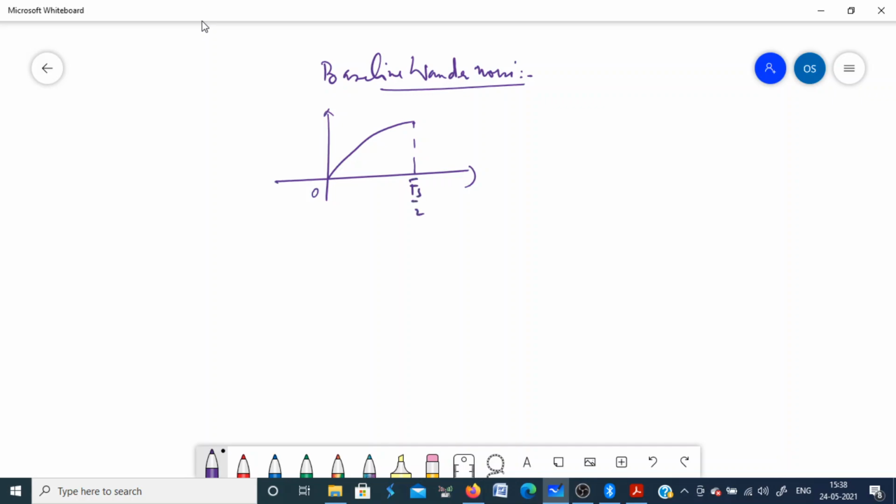Okay, then we modified it somehow. We got another response like this. So at a frequency of fs by 2, there is a null point at 0, so the gain drops to 0 again at fs by 2. So somehow the high frequency noise amplification problem was solved.